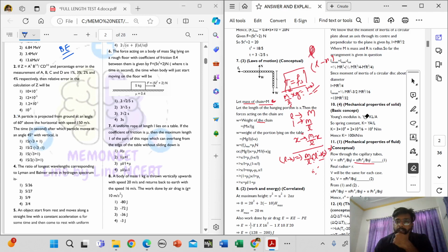There is contact with the surface, so we have a normal force in the upward direction. Then we have a downward force, mg. Same here, that is mg. There will be a friction force F, equal to mu times the normal force, which is mg. So here W is equal to the maximum friction Fs, that is mu S into M.